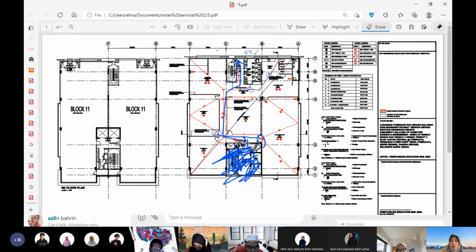So that is why you need to design another fire staircase here. This is the fire staircase, and this is the fire door here, and the distance is a short distance. So meaning that within 1 minute people can arrive at the fire staircase and evacuate.